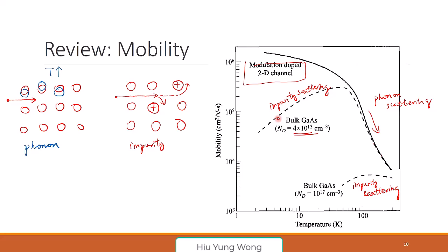So now go back, we talked about ballistic mobility, remember, before the midterm? Ballistic mobility is when your channel is so short, I don't even feel scattering before I reach the drain. So I actually don't have a real mobility, but we come up with an effective mobility, or we just call that ballistic transport. Do you see what I mean? Yes. Okay. Make sense? Yes, it does. Yeah, very good question, right? So don't take things as they are, right?